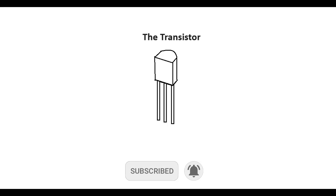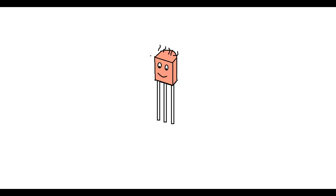Keep in mind, too much current or voltage may damage or permanently destroy the semiconductor chip that forms a transistor. The transistor may become hot and operate improperly. If the chip isn't harmed, its tiny connection wires may melt or separate from the chip. Never connect a transistor backwards.